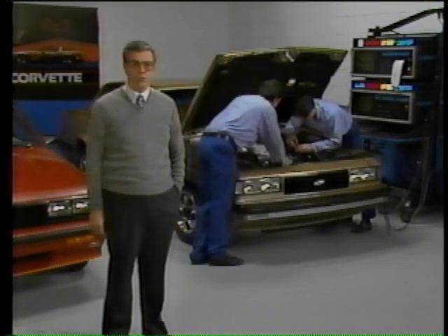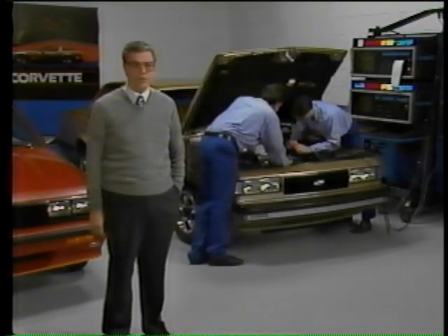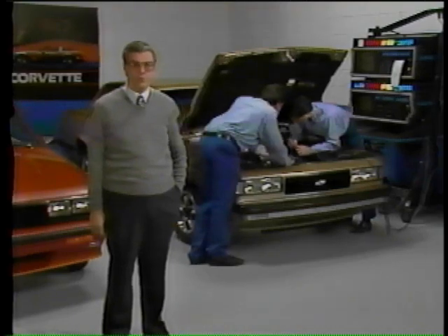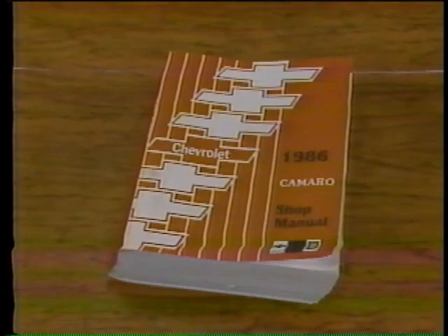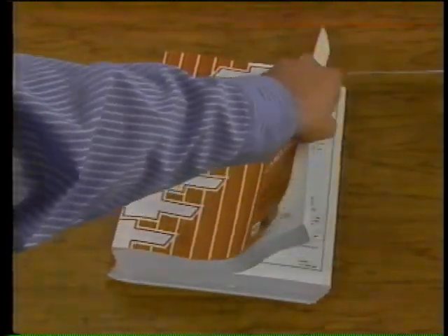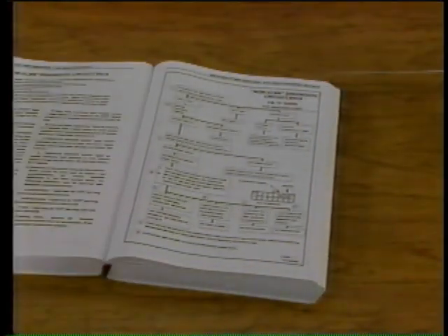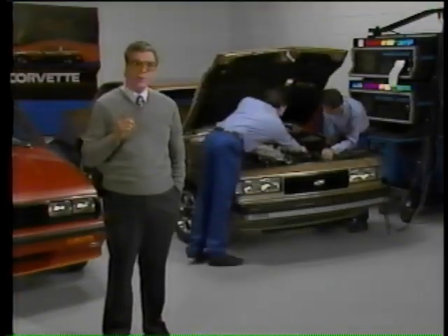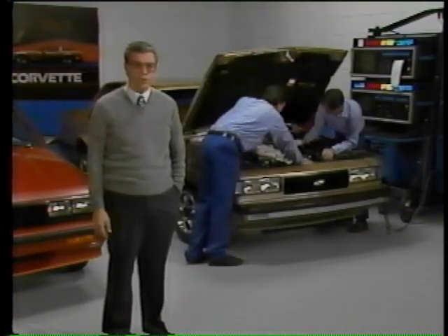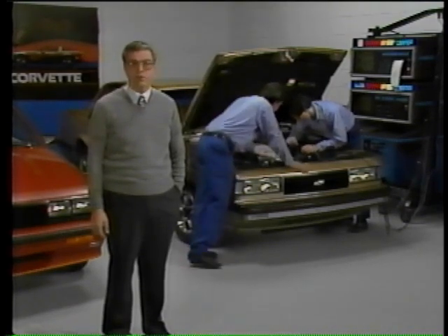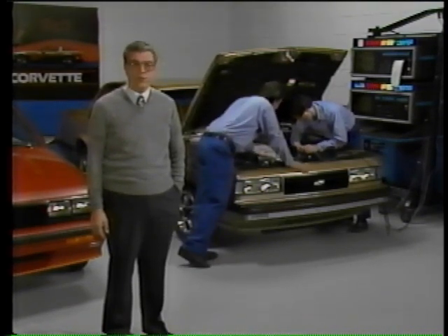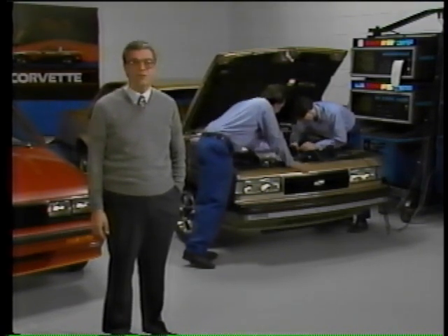The scan tools that developed were capable of reading the data that was available from the computer via the ALDL. In 1986, the shop manual recognized the diagnostic value of scan tools and included some scan tool steps in drivability trouble code charts. However, the number of scan tool steps was limited due to the nature of the 1986 and earlier computer command control systems. But things have changed for 1987.